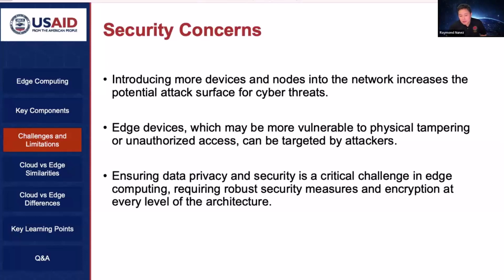So again, you might want to consider privacy and security when deploying these kinds of devices that do not have physical security. Problem: if you enable security and encryption on most of these devices, there will be a corresponding penalty on battery requirement, because the processing requirements of these edge computing devices would also increase. So you get additional heat, and with that additional power consumption and reduced lifespan of that device. So again, there's a lot of pros and cons that you need to consider.